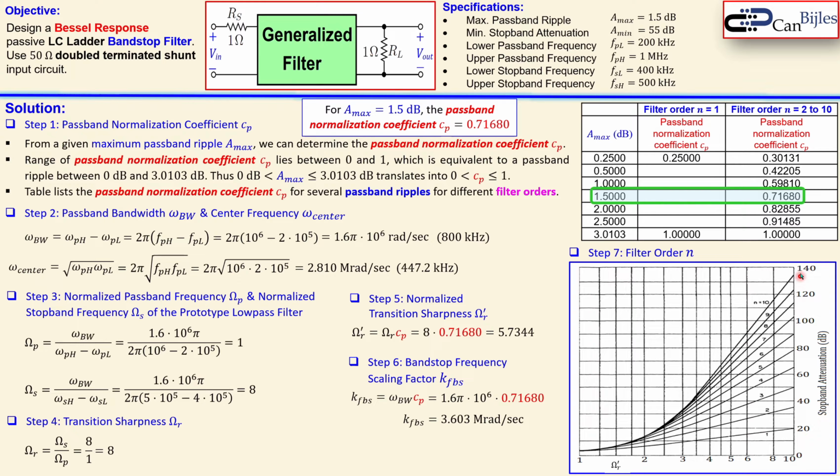And in the vertical axis, we have now stopband attenuation going from 0 to 140. You see here lines that will then also determine your order. So first order, second order, third order, fourth order, etc. So we have lines here. How do we determine now, carefully, our order? Because we said it must be between 2 and 10, so second or 10th order. Exactly, we don't know yet.